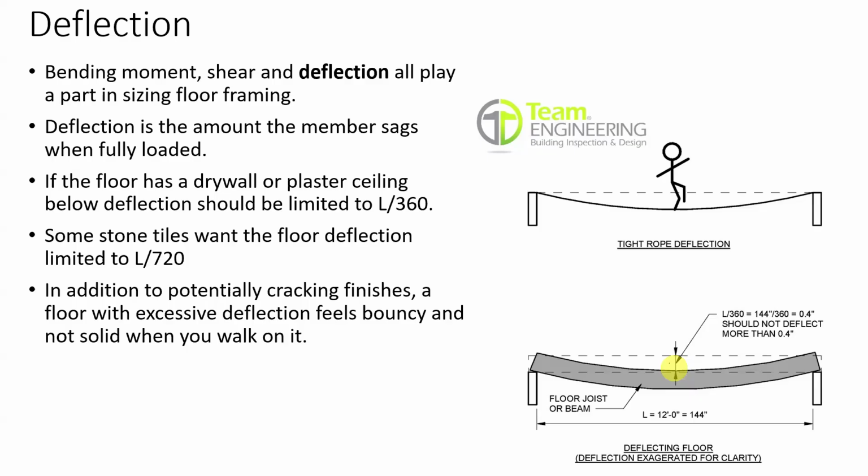So as we're going to find out once we get to Forte, you can have a structurally sound floor that's never going to collapse, but people don't like the way it feels when they walk on it. It doesn't feel solid, okay? And so the people that make the wood I-joists, the Weyerhaeuser company, have actually done tests and they give you a rating on how stiff the floor feels. And we'll get into that when we get to the Forte software.